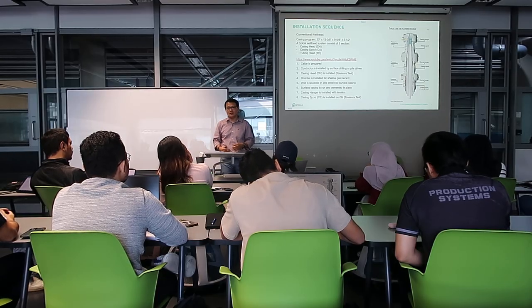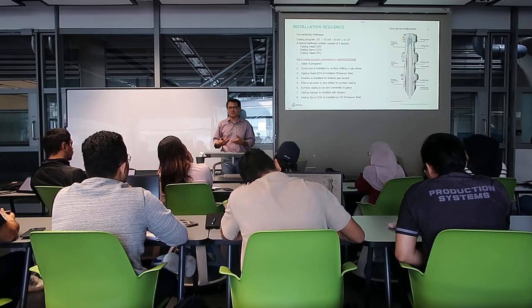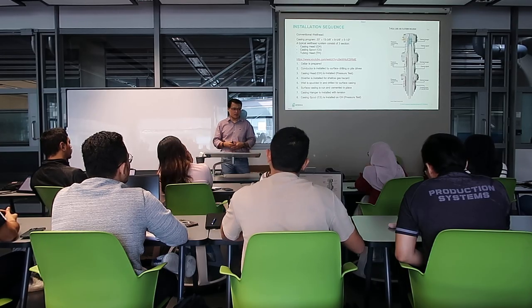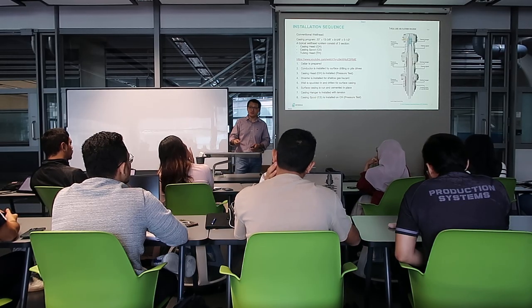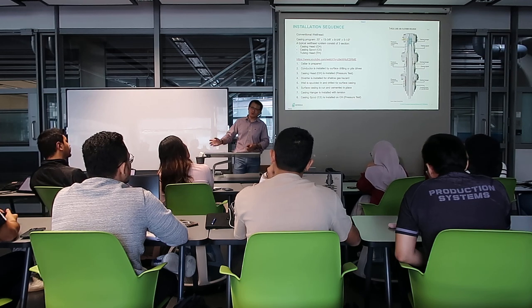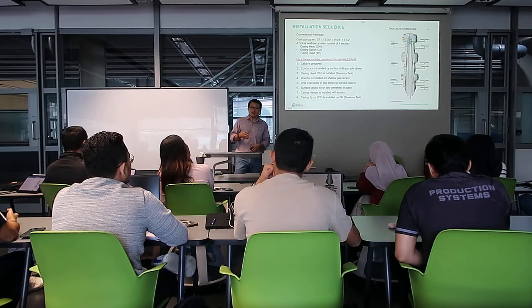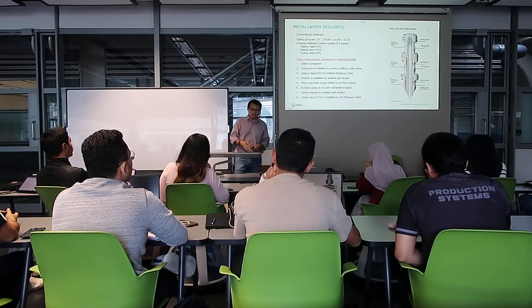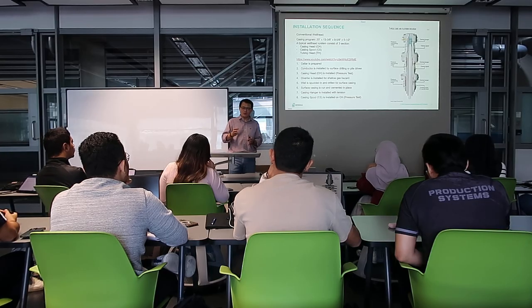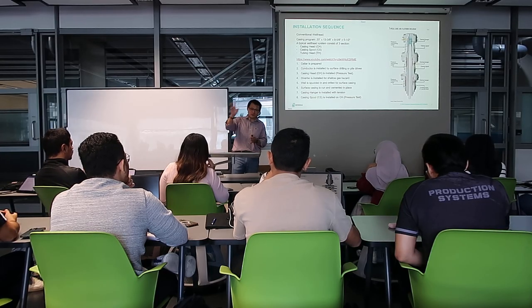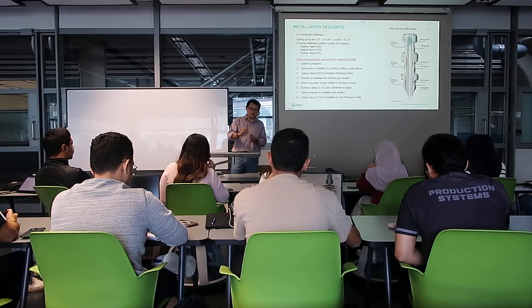But I think nowadays we introduce more facilities. I mean, later I'll show how to do the testing as well. So we try to test it as soon as possible, so we don't need to go back and redo things. For example, if we can land the casing hanger, then we test it, compared to landing the hangers, putting on the next wellhead, and only then testing it.